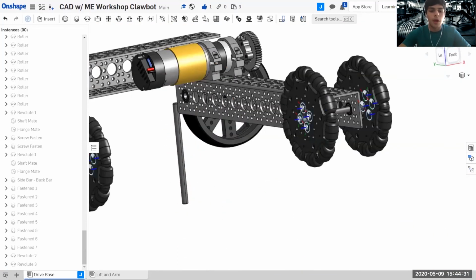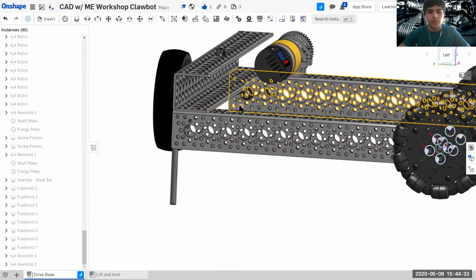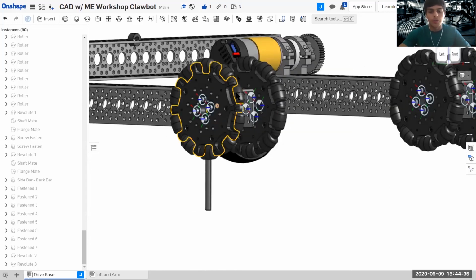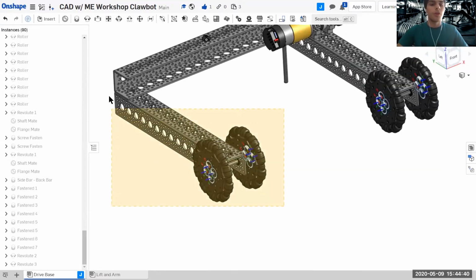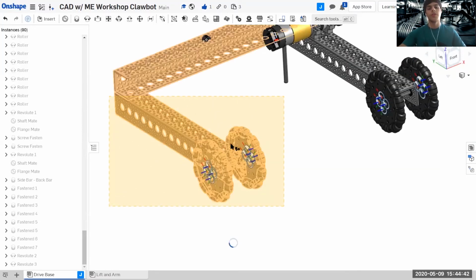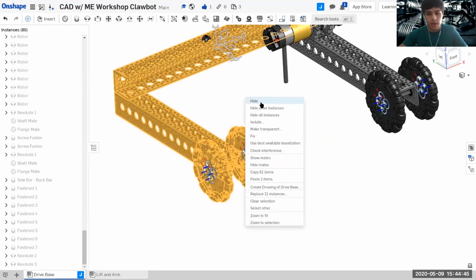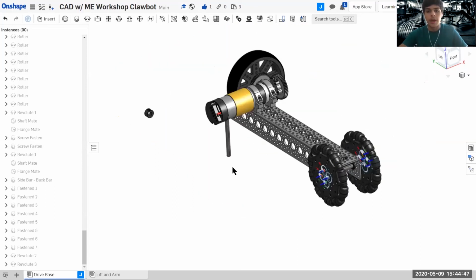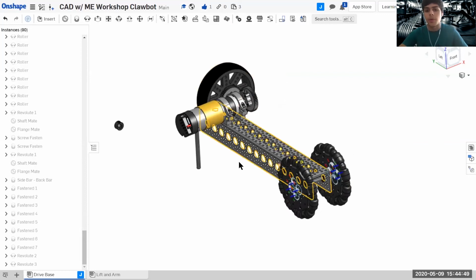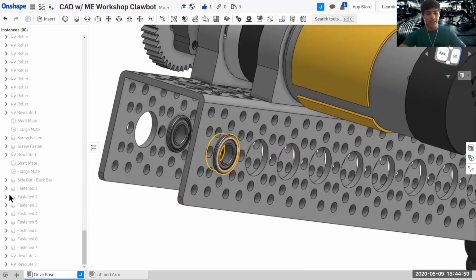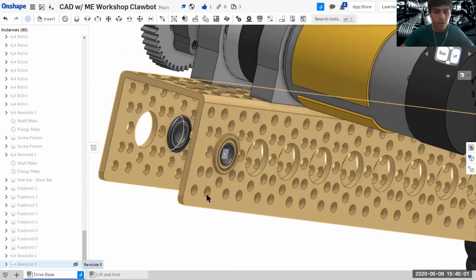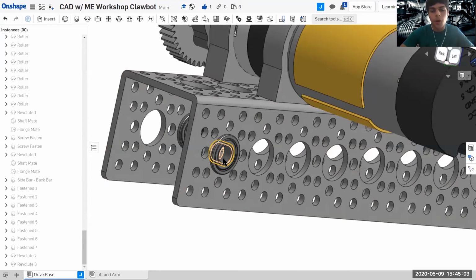If you're bothered because you're trying to, let's say, put this bearing here and this wheel got in your way, you can simply drag select whatever parts you would like. Once they're selected, you can right click and hit hide. Once you do that, it just displays the part of the assembly that you were working on mating. So now that you have these two bearings here, okay, I have made a mistake. It appears that I have mated the wrong one. I've put the wrong bearing in the wrong hole.